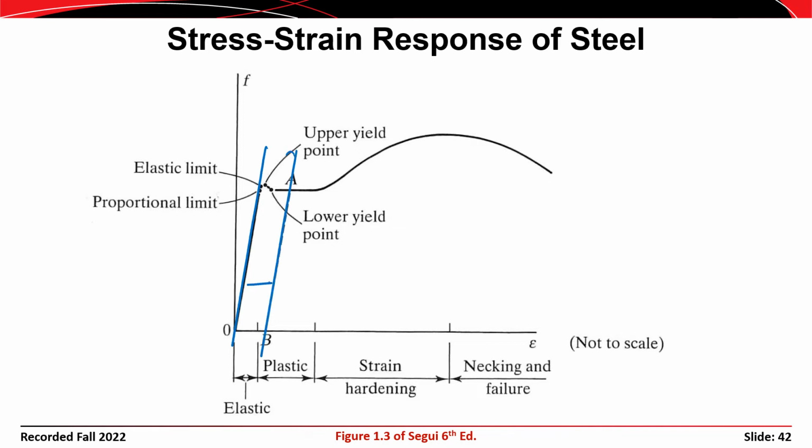That dimension is usually 0.002 strain, and strain is dimensionless. So that is actually equal to 0.2%. So we have a line that is offset by 0.2%. So we refer to this point up here at the top. Let me get the red pen color. So this right here would be, let's see, and then we strike that over here to the axis on the left. And this would be F sub Y. That would be the 0.2% yield stress for that material. And I think you're asked to do this in one of your homework assignments.